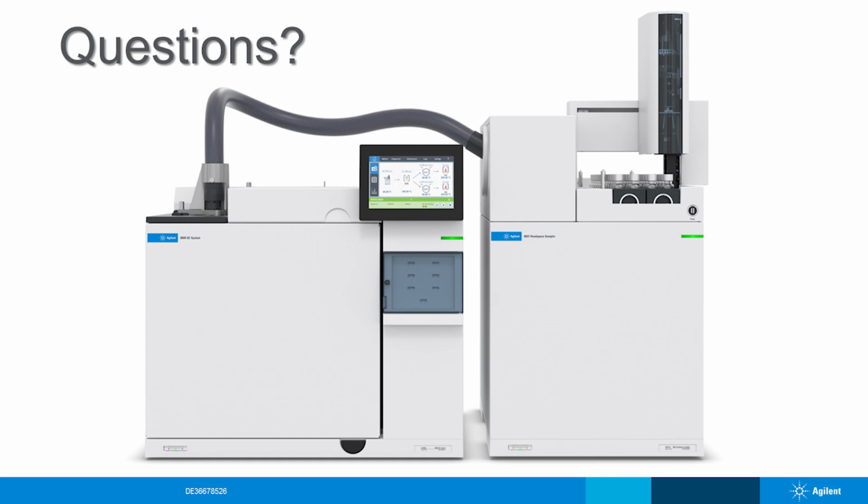I believe it's a light tan color, and it goes around the metal right at the exit of the transfer line. So you should be able to visibly see it if you pull your transfer line out of the inlet. But apart from actually taking it out of the GC, I don't know of a way to determine that.